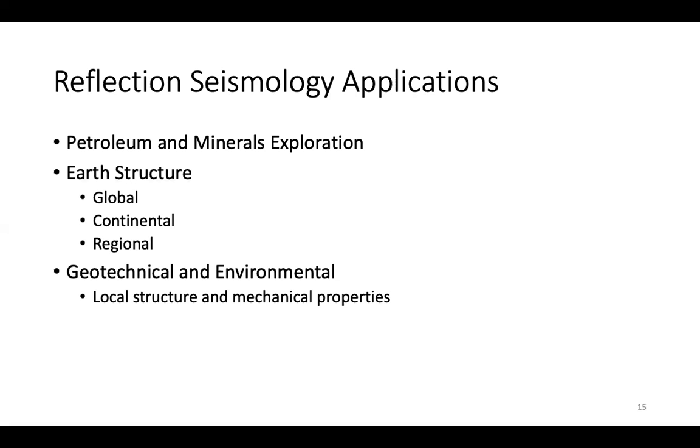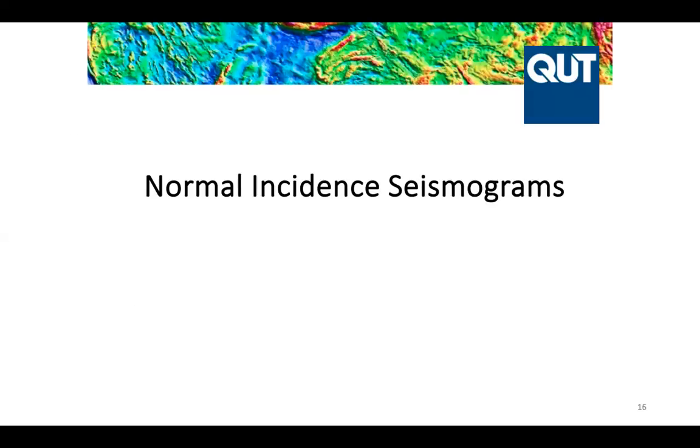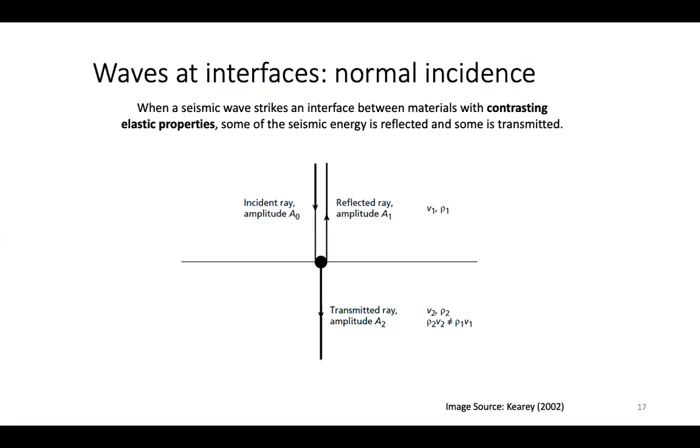If you're going to put in any big infrastructure, you generally do some type of survey, and in the marine offshore environment, these sorts of sub-bottom profiling surveys are bread and butter if you're putting in a desalination plant or laying out a pipeline, and I've been involved in a few of those works. You absolutely need detailed sub-bottom profiling information over the entire area so you can make informed decisions about how to engineer a structure. So let's talk about what we actually get in terms of reflections to start with.